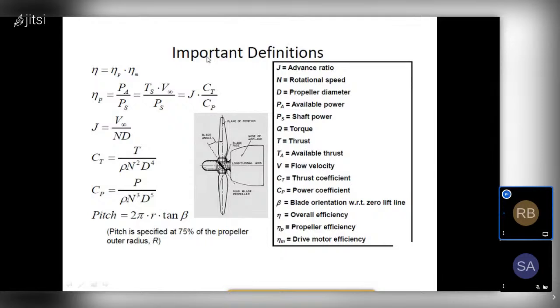Blades tend to stall, so it's very important to know the axial flow velocity of that propeller, and the diameter. Larger diameter tends to give higher efficiency because of increased mass flow rate, right? So usually the best overall propellers have a pitch to diameter ratio of 1.